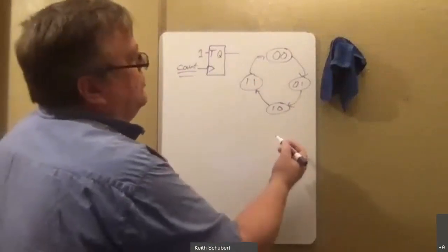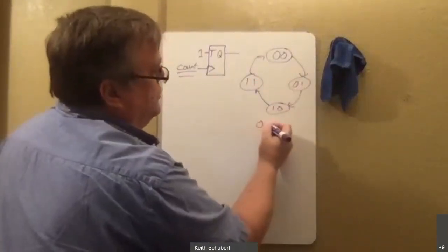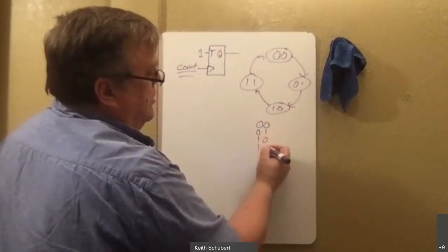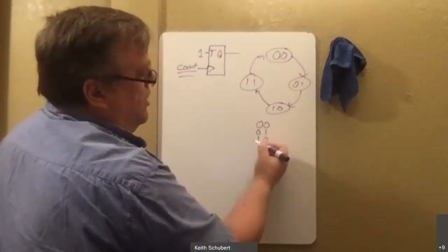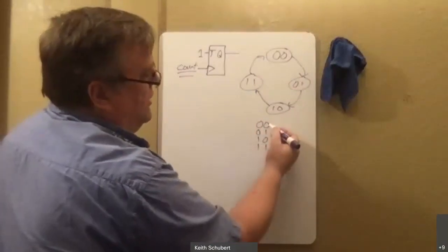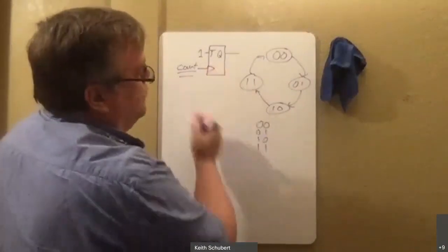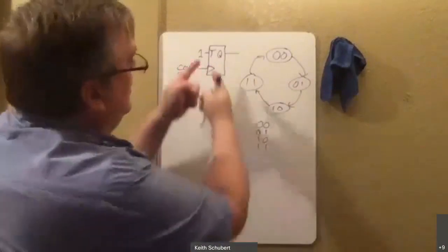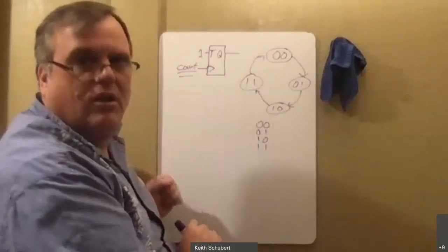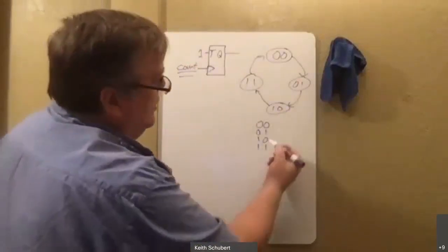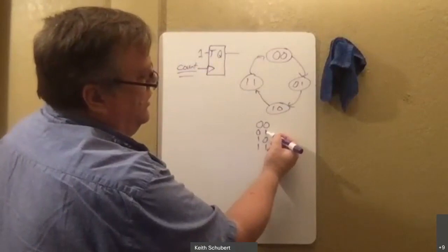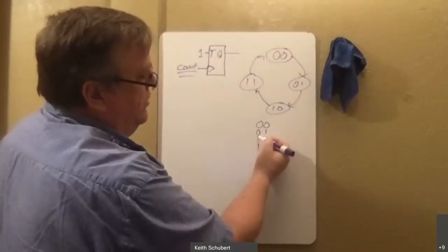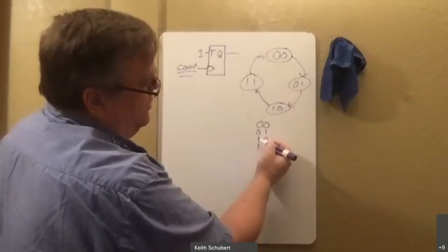When I look at what I need to do here, it's going 0, 1, 2, 3. Well, this is my least significant bit, this one here. And it's doing that 0, 1, 0, 1 ad infinitum, exactly what this does. And then every time this is a 1 and turns off, this right here should turn on or flip.